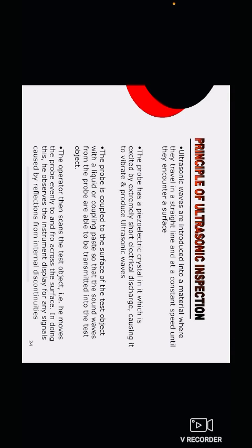The operator then scans the test object. He moves the probe evenly to and fro across the surface. In doing this, he observes the instrument display for any signals caused by reflection from internal discontinuity.